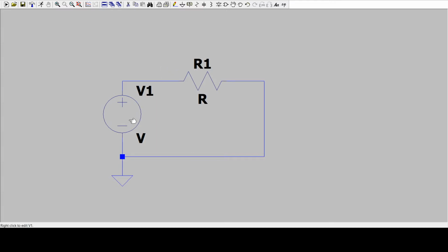So next thing we need to do is give these some values. So let's call this 9 volts. So if we have 9 volts here, and I'll explain how I got to that here. With our resistor, if we right click it, or 3-finger click in the Mac case, we can specify a resistance value. Now, it might be tempting just to put something like 2, that would make things easy, but just something to keep in mind due to power constraints when we're dealing with circuits, we're oftentimes dealing in the kilo ohms or the high hundreds of ohms. So that's the convention I'm going to follow here.